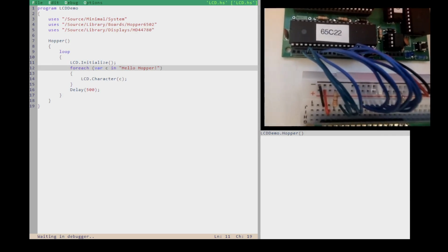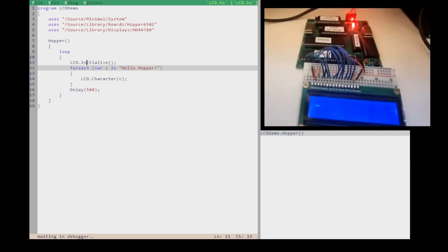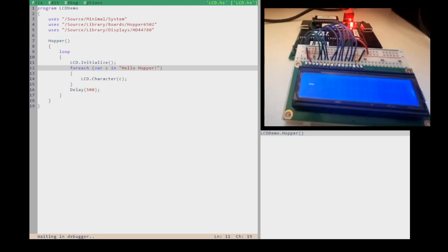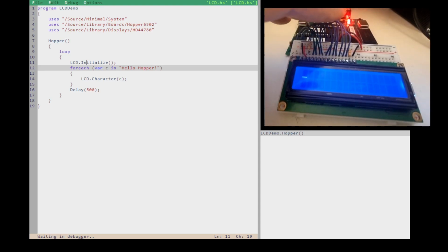And you can see I've missed a few pins, and that's because those pins are used for other things. So the parallel port pins are used for the user button, I2C, and the built-in LED. But that's 4 out of 16, which leaves us another 12. And for this device, we've got 8 data lines and 3 control lines, so it uses 11. You can also run it in 4-bit mode, 4-bit parallel rather than 8-bit parallel.